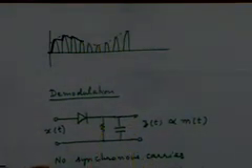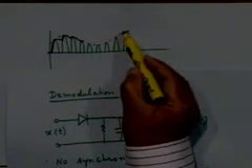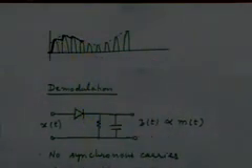As you can see, this charging and discharging phenomenon under certain conditions would produce an output which follows the envelope, right? Approximately there will be some ripple in the output, which you can always remove by a suitable low pass filter.